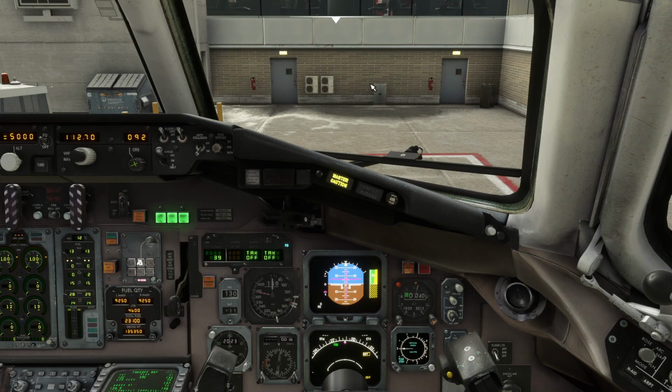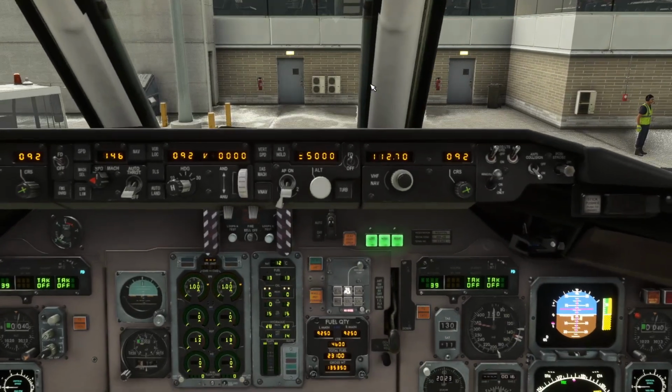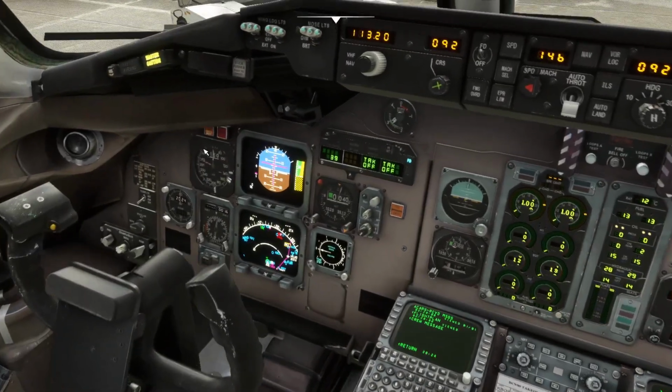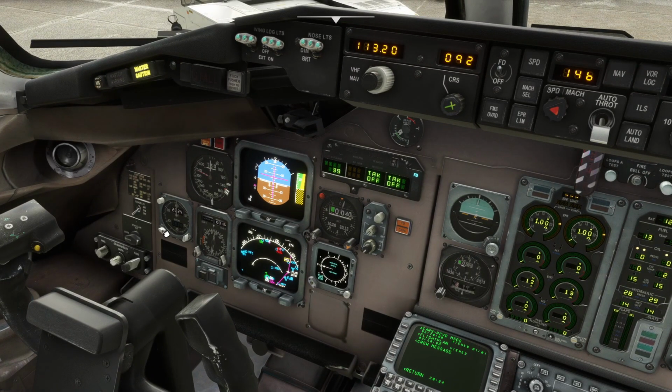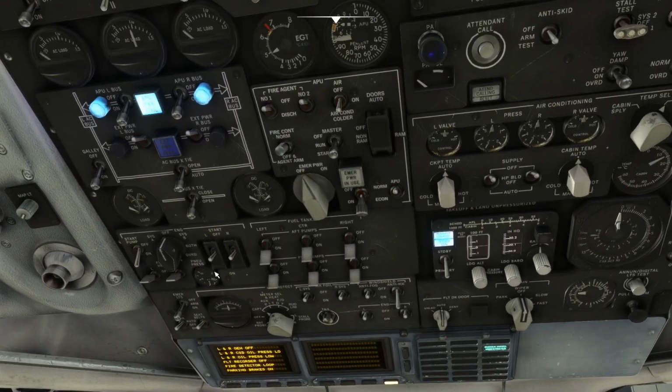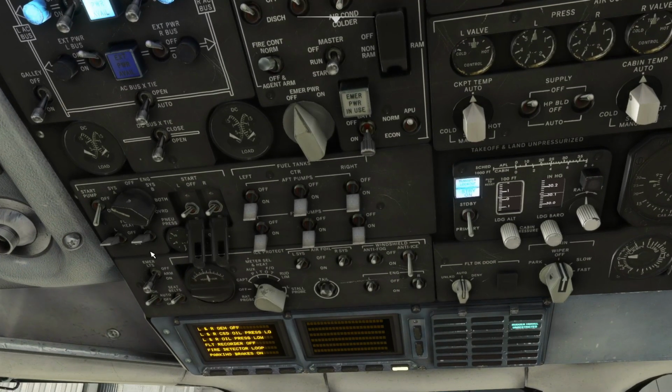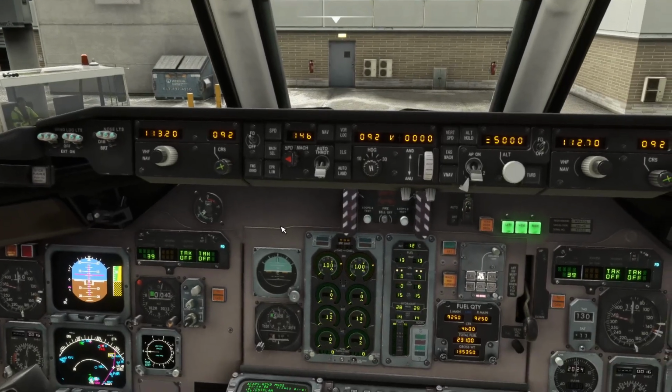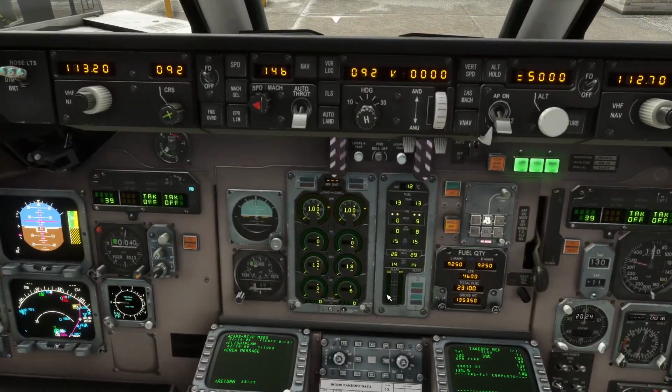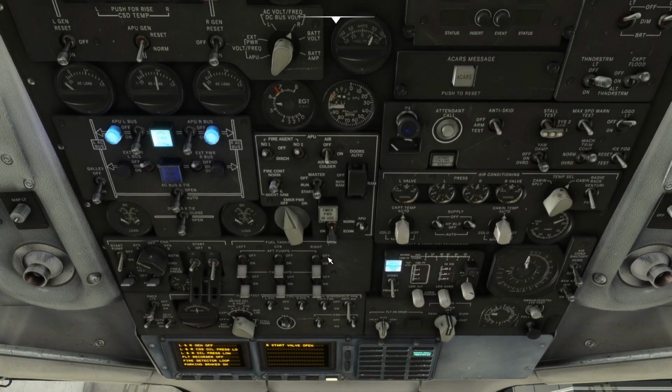I've tried to diagnose the problem, and nothing is working, so we're going to do this like they did it in the 80s, and we're going to do an on-stand startup. Block timer to run. Open up these two covers. System A or System B. Start right. And you use the scroll wheel to hold it down without having to actually hold it down. Observe the N2 that is rising.